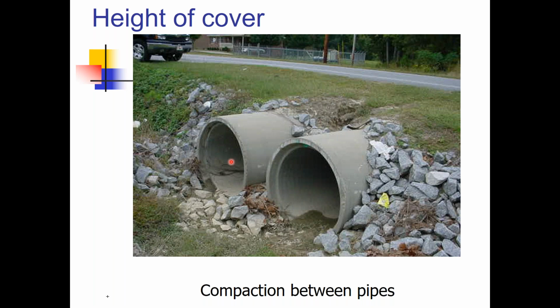Okay. And each one of those are very good points. This would not be the design that I would want to have, because you can already see there's some erosion there, there's some give. It looks like they tried to cover it a little bit. However, if there's any give down here and that pipe moves or gives, it's going to get out of alignment. It's going to cause water not to flow properly. It is incredibly difficult to get compaction between these two pipes on any level, which means it may not be setting them on a solid foundation, with as much density as possible.